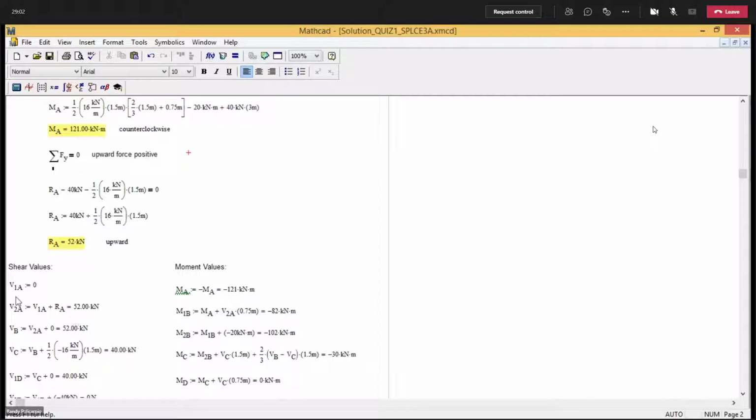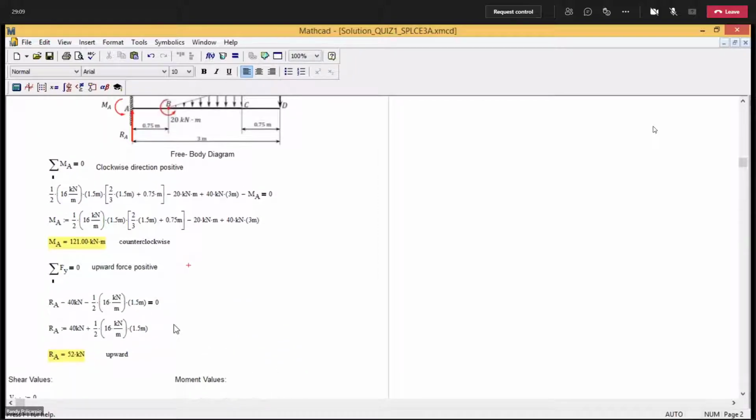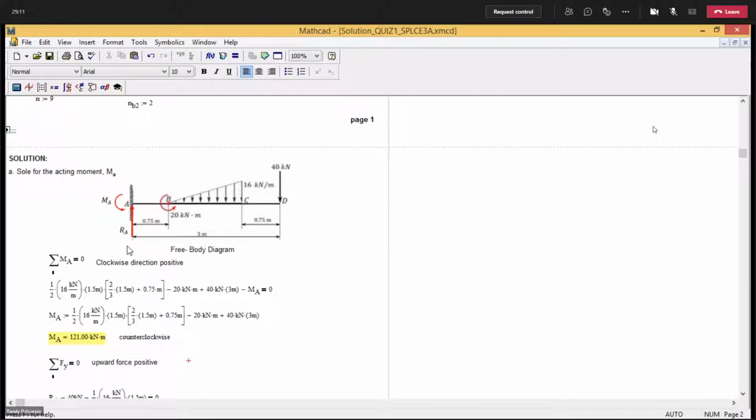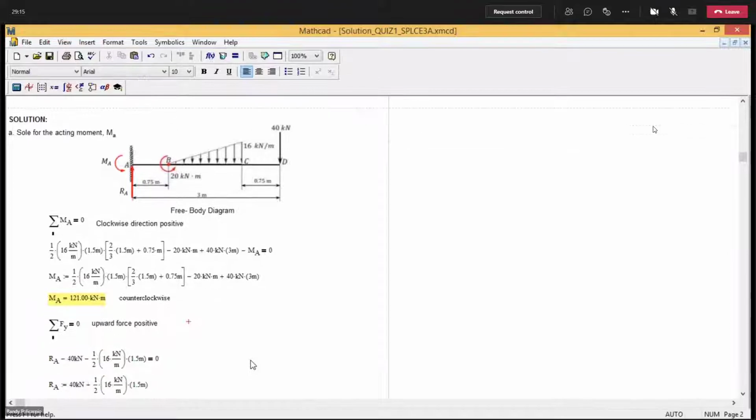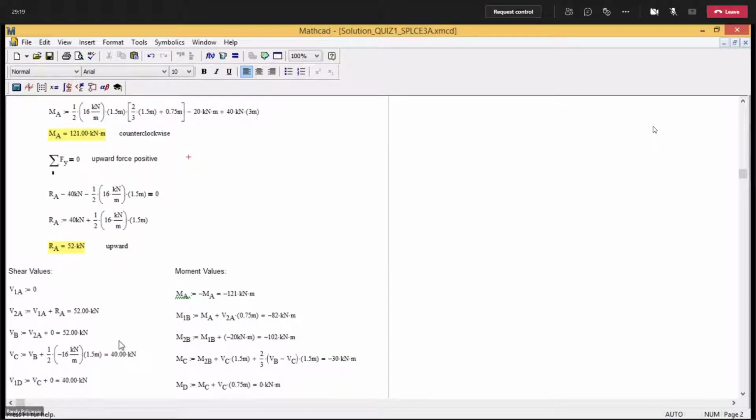So you're going to add your initial shear, then you add your concentrated load. Our concentrated load here is acting upward, and the assumption that I presented in mechanics of deformable bodies is that upward forces are considered positive in terms of the sign convention.